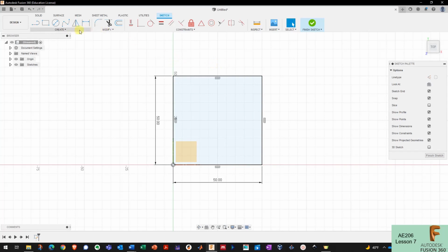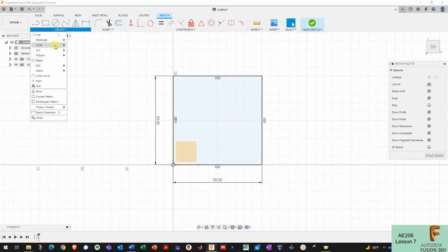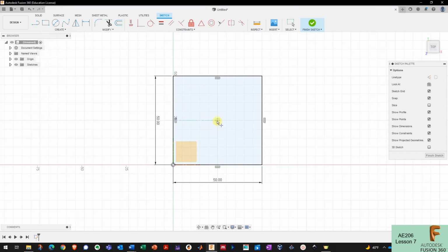Okay, now for this method of creating an octagon, I'm going to copy this square and rotate it 45 degrees to the first one, and then I should have an octagon after that. But I need to make sure that both of them are aligned perfectly. So I'm going to create a point, and I'm going to put that point in the center of this box, and that's going to be my alignment point for aligning the two boxes.